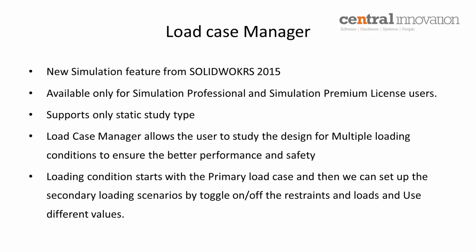This load case manager helps you to create multiple loading scenarios by toggling the fixtures on and off, by changing the loading condition, and creating a new, different load combination. You can also create a loading combination. Let's say I have combinations 1 and 2. I want to combine 1 and 2 together and create a third combination. You can do that by using the load case manager.